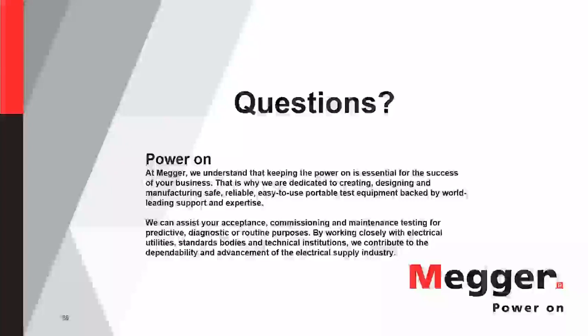Another question is, based on your experience, is it possible to use a linear transducer on a live tank circuit breaker? It depends on the circuit breaker. I have seen it used. If it's a live tank, a minimum oil circuit breaker, then that was generally what people would use. On the SF6 style live tanks, more often than not, I see a rotary transducer used on those. But you can hook up a linear if you would like.